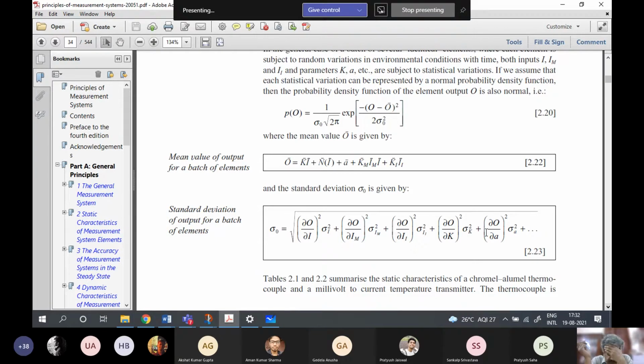I don't know if some of these machine lab ammeters have a zero adjust mechanism. Before taking a reading, you can actually open the ammeter and adjust for zero, of course by eye estimation, and then connect the ammeter. Then for that individual ammeter, for that individual measurement situation, you have adjusted the offset.